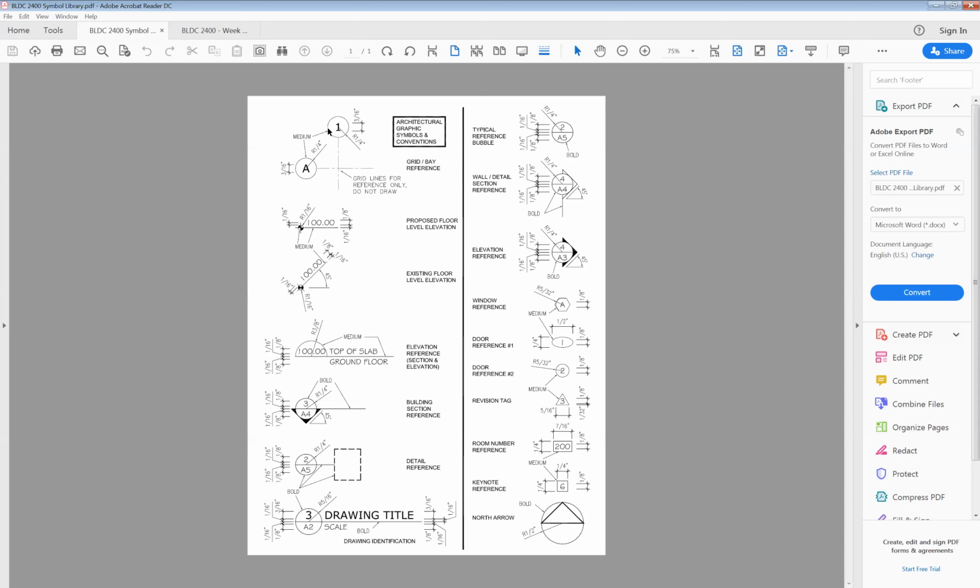These symbols, in their most basic form, are really a circle and another circle. We can keep it simple. Remember, you don't have to do the text, the dimensioning, or the hatching. We're only drawing shapes. The radius for these circles is 1/4 inch for each.